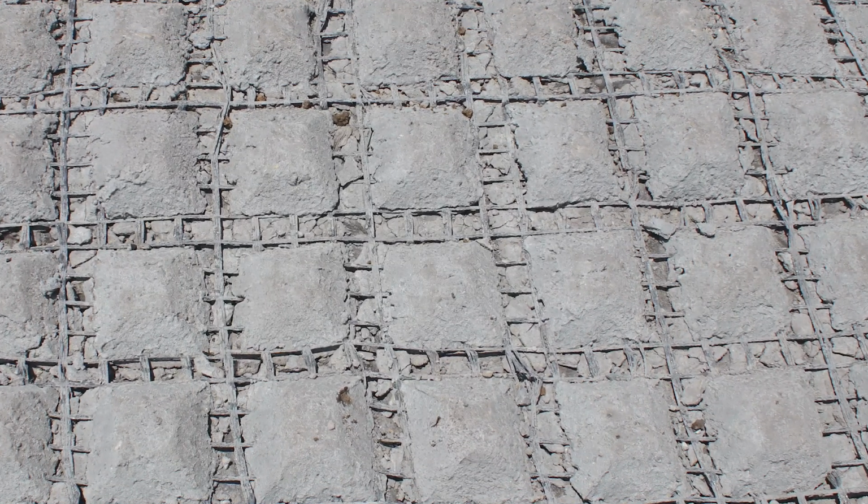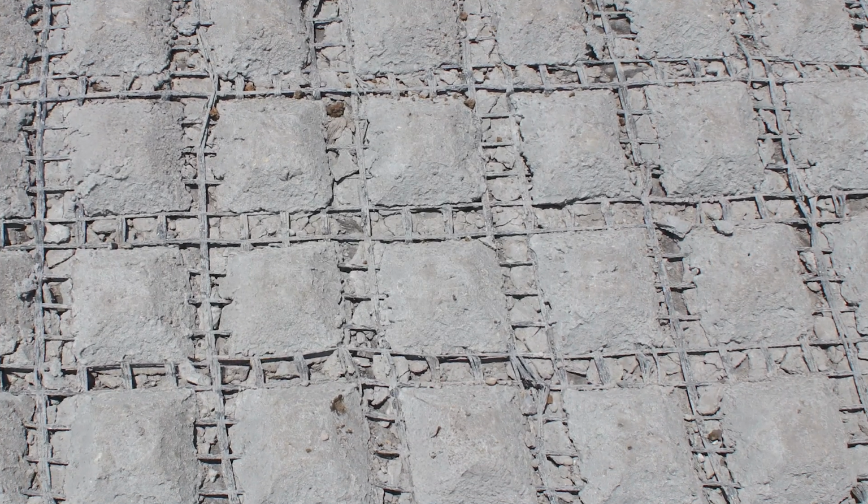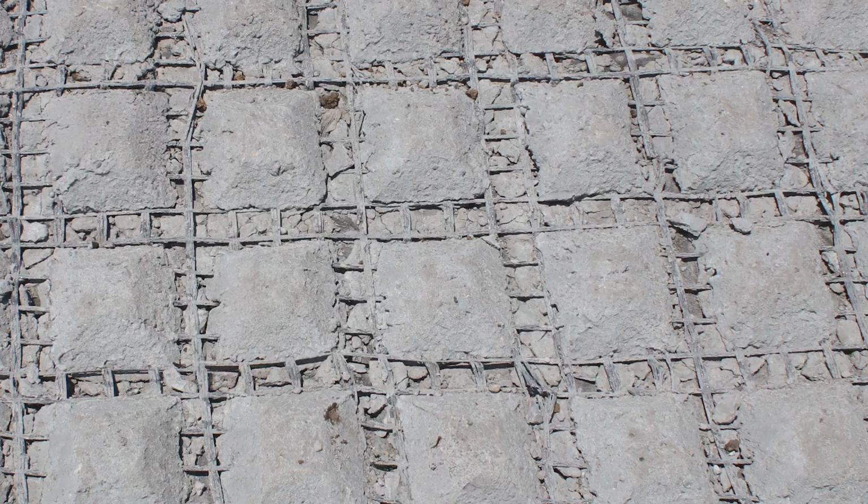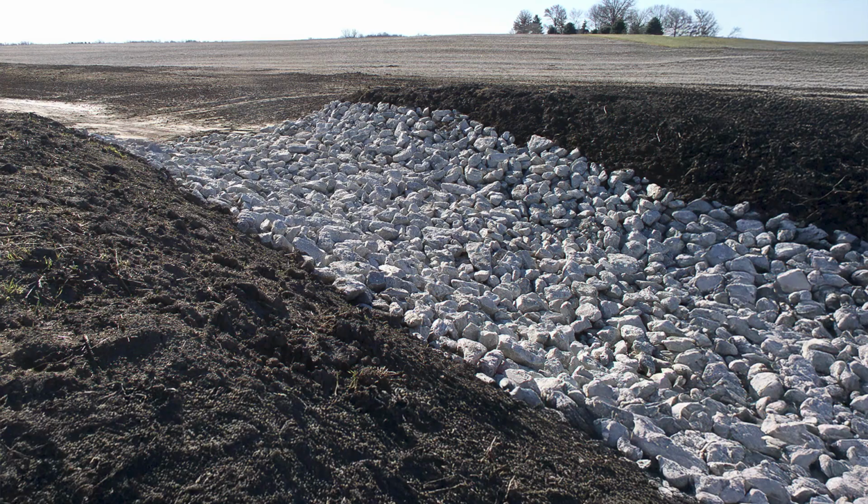The tied concrete block mat did not have a significant difference in cost, but does require much less labor to install than the rock or block alternatives. A rock riprap chute would also require a larger footprint area than the other materials to address the same erosion. And even though the rock is a natural material, it could have a greater visual impact because of the extent required. Maintaining or enhancing the landscape is an important aspect of the NRCS mission.